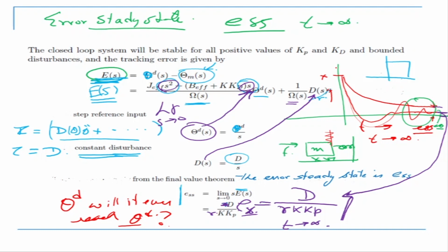Now, how can you reduce that error? You can see that this steady state error is directly proportional to D, the dynamic torque. And D is equal to M theta double dot plus V theta theta dot plus C theta. What does the dynamic torque depend on? We studied this when we looked at dynamics. We saw that it depends on acceleration, on inertia, on Coriolis and centrifugal terms, and on position. So if the manipulator is moving very fast, you'll have more error. If it's moving slowly, you'll have less error.